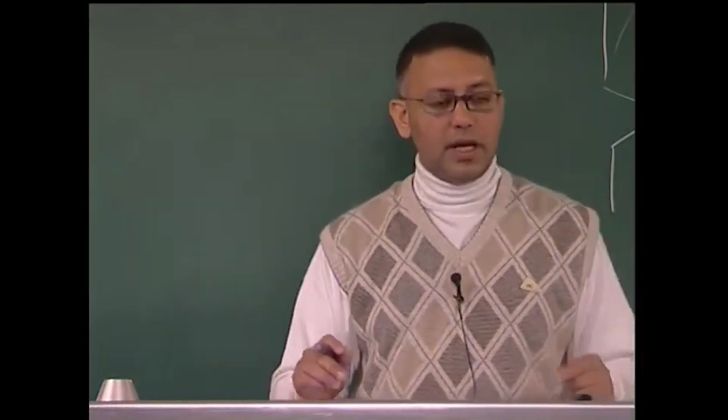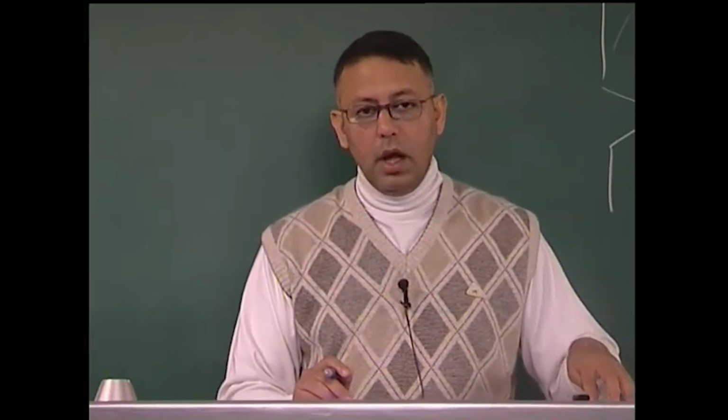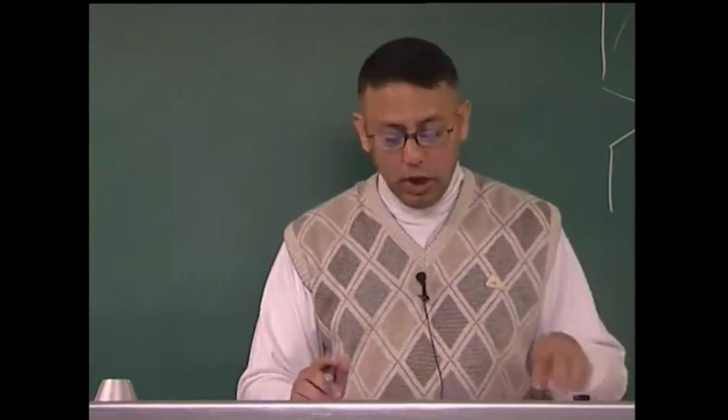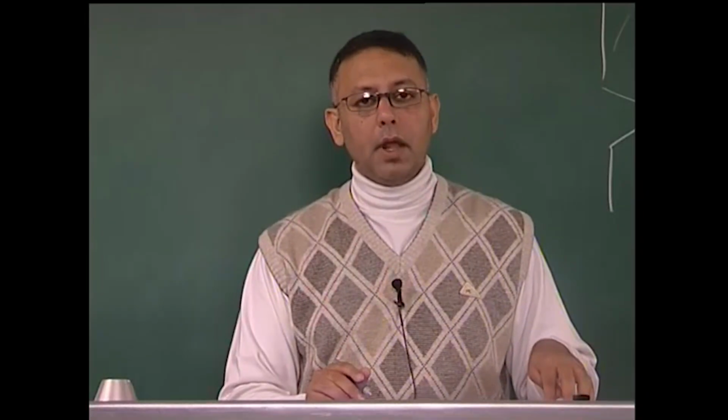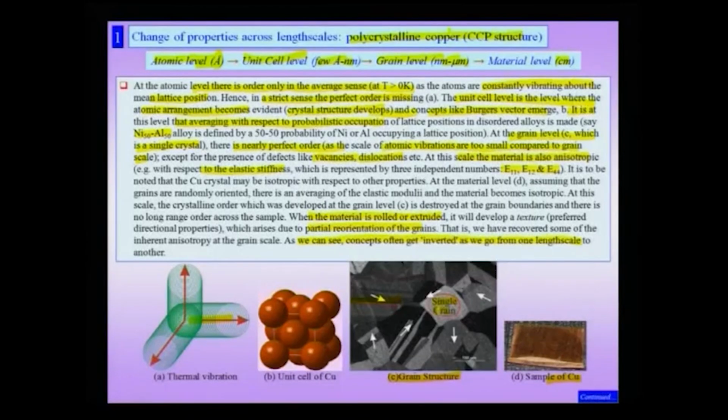However, at the grain length scale, we would notice there are other defects which come into play, which are crystallographic defects like dislocations, voids, etc., or even stacking faults or twins, as the photo micrograph shows here, and therefore again I am dealing with certain other kind of disorder at this length scale. Now, if I am talking about the single unit cell level, I would notice that my system has to be described by anisotropic properties, which is what is seen at the single grain level. But when I go to an entire component level, I see that now my material behaves isotropically, unless of course it has some kind of a texture.